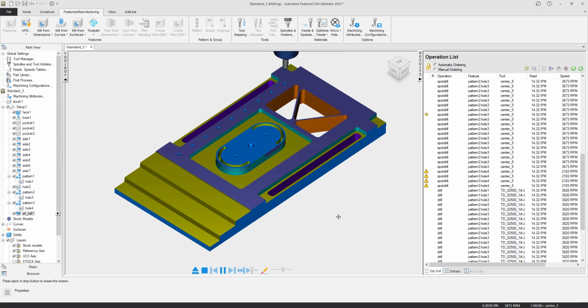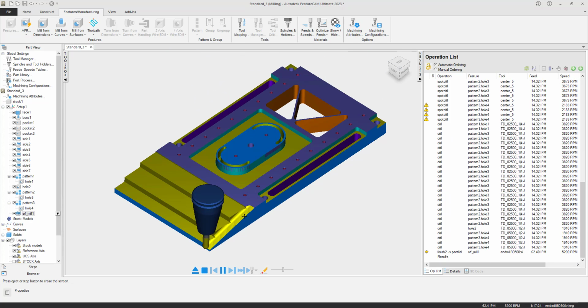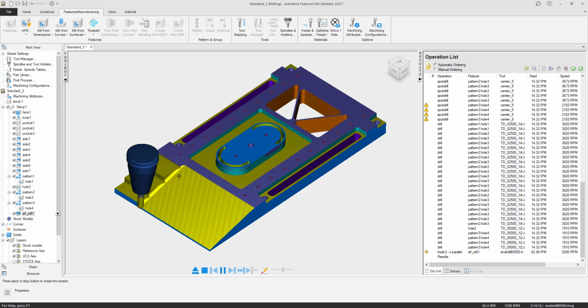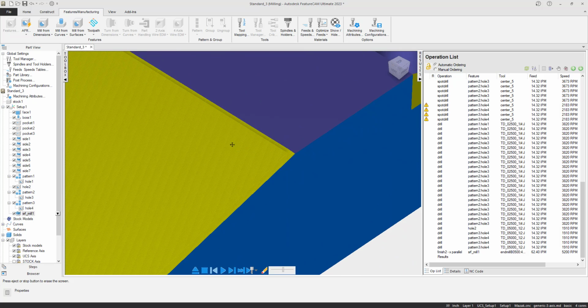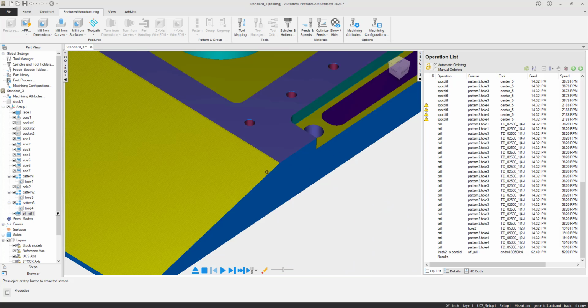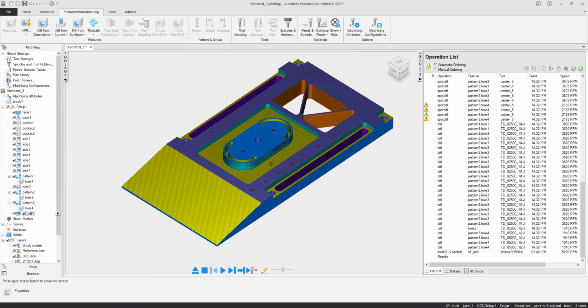And now when it comes to it, it might not seem like it takes longer, but we're going to see. There it is. So I didn't change my speed at all, but look how much longer it's taken to make these parallel finishing moves. Now when I zoom up on it, woo-wee, that looks a lot better right there. So that means I'm not going to have to do a lot of deburr work, but it's up to you to find out how much deburr work you're allowed, because this might run for a long time. So let's find out exactly how long it runs for.